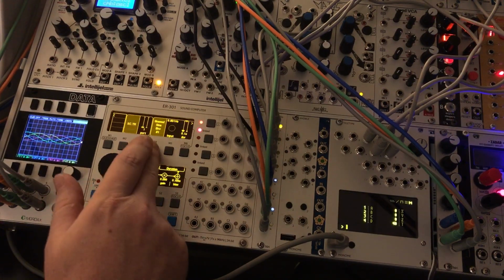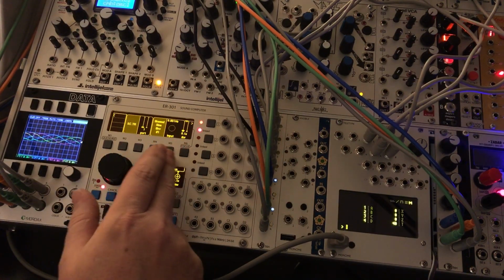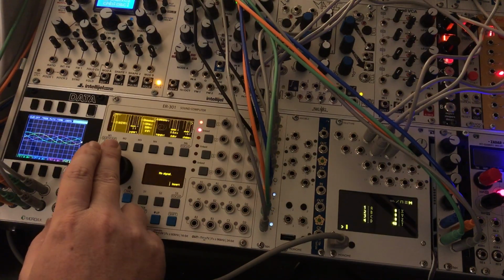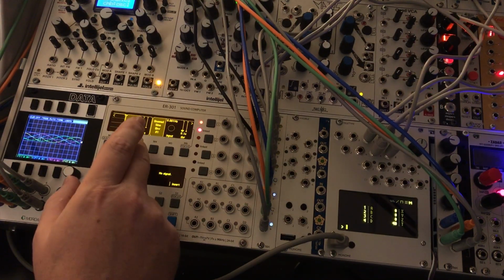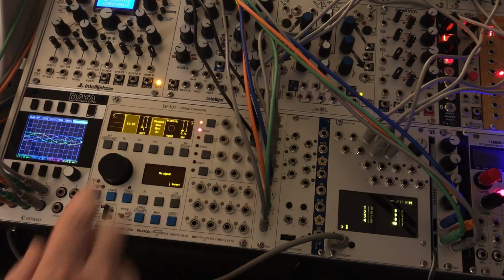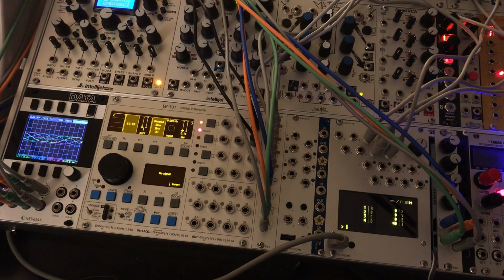In most cases here, I'm using this skewed sine envelope, which is kind of a sine-shaped envelope with a fixed duration. And these are being triggered over the I2C bus by these SC.TR units. So this one is on port 1. If I issue SC.TR.PULSE 1, we'll see it fire, and it produces a sound. It triggers that envelope and lets the sine oscillator through.